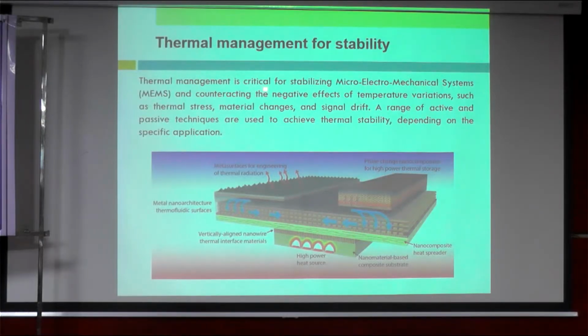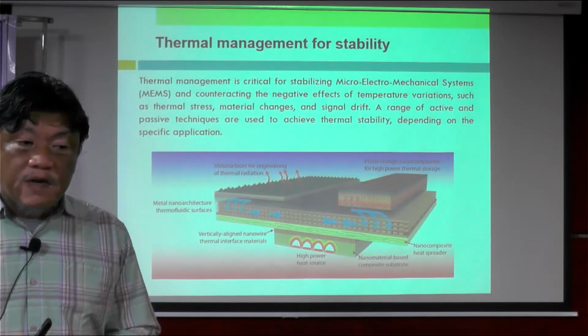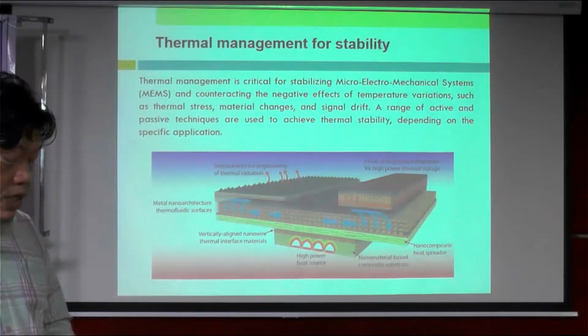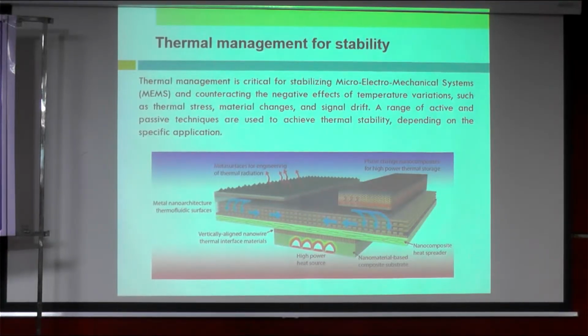The thermal management is critical for stabilizing microelectronic MEMS and counteracting the negative effect of temperature variation, such as thermal stress, material changes, and signal drift. So a range of active and passive techniques are used to achieve thermal stability depending on the specific application. So active meaning we have some means of forced cooling, etc., in order to have the device in a controlled temperature.